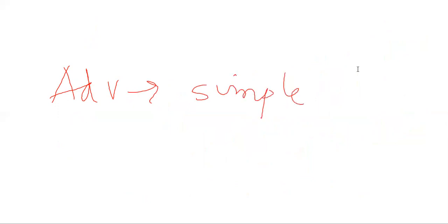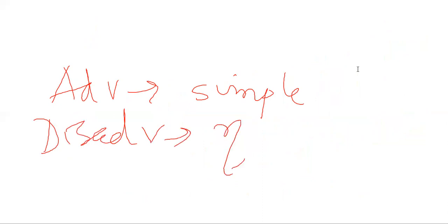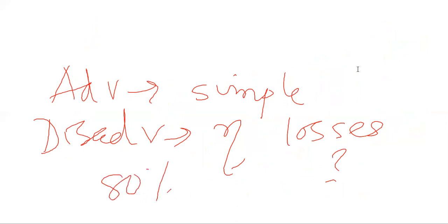The disadvantage is that you simply know the efficiency and you don't know where the losses are happening. Let us say that you get some efficiency of 80%, which is the efficiency by direct method. So what you know is that 20% are the losses.